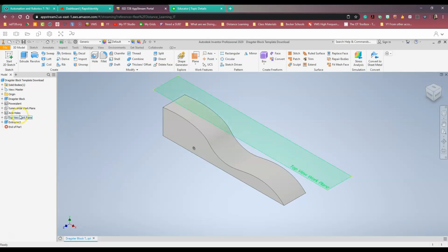Okay, so hopefully you tried out those steps. Now, I'm going to go to the axle hole portion and I'm going to move that front axle. Notice when I'm over here on my model, if I hover on axle hole, I have two holes that show up green on my CO2 car. I'm going to actually move both of these axle holes. I don't want this rear axle to be quite so far from the back of my car, so I'm going to move both of them.